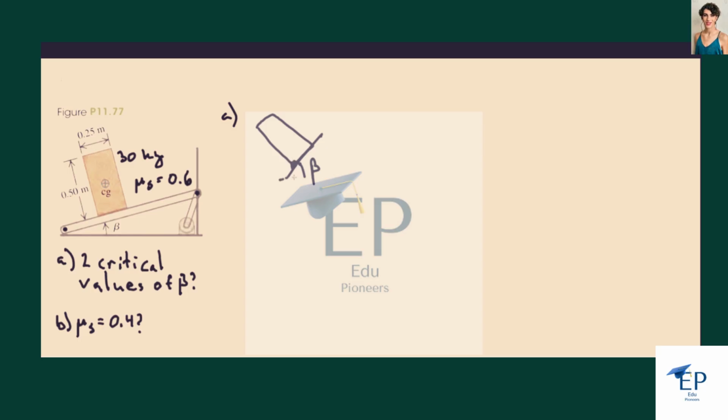And so if we look at the torques involved, then the torque from the normal force and from friction are zero because they're at our origin point. And so since the torques have to all add up to zero, then the torque from the center of mass also has to be zero, which means that it's pointing straight down through the point A.